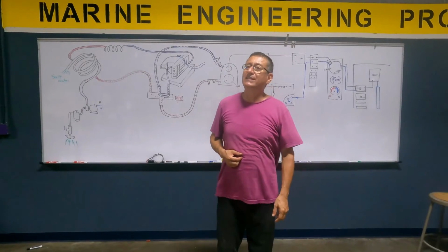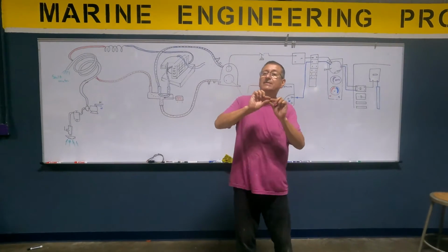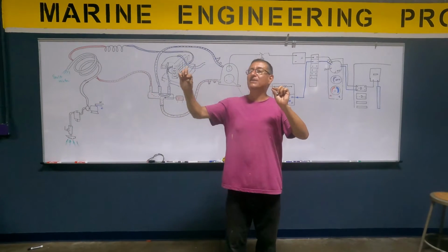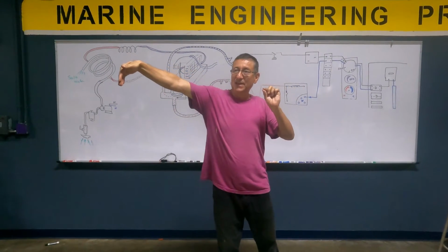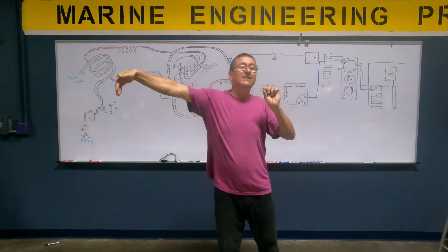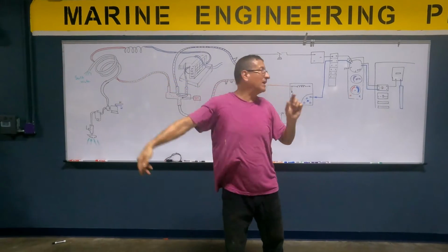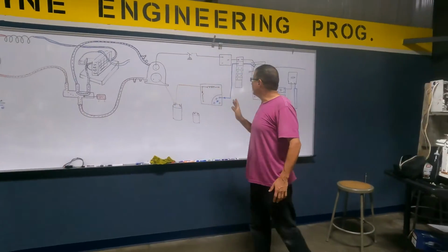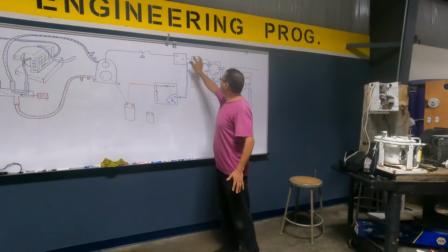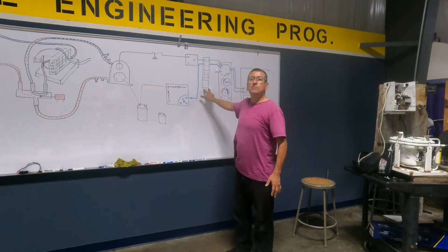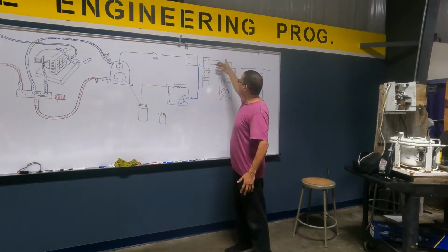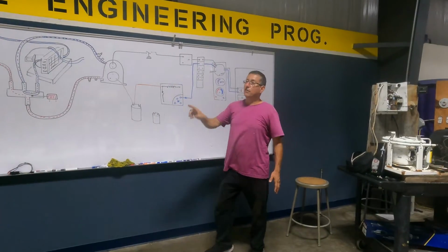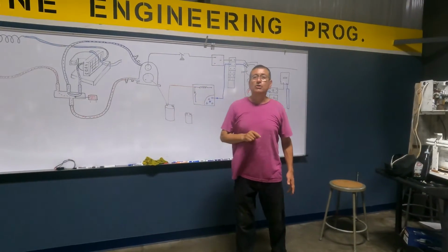And that control, the thermostat, is a capillary pipe with a bulb, and that bulb is located in front of the air filter, no? And it's connected here. Okay, the rest is the control box. This is a junction bar where you enter the power, and the power is distributed in the different components of the control box.